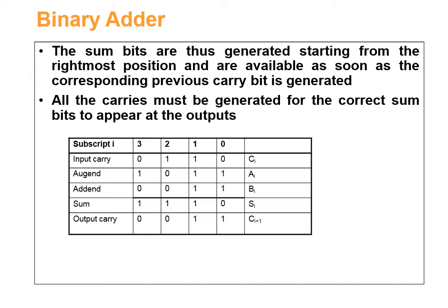Observe that design of this circuit by the classical method would require a truth table with 2 to the power 9, equal to 512 entries, since there are 9 inputs to the circuit. By using an iterative method of cascading a standard function, it is possible to obtain a simple and straightforward implementation.